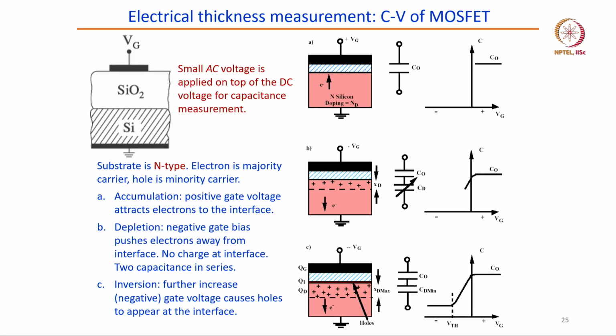So, this being the last slide, what we have seen in this lecture is how silicon dioxide is grown on a silicon wafer using thermal oxidation. In thermal oxidation we have two techniques, dry oxidation and wet oxidation. Dry oxidation is very simple, Si plus O2, but for wet oxidation we can use water vapor or separately mix H2 and O2.